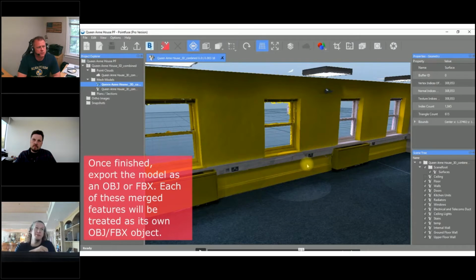One interesting note, mobile scan data meshes much better than terrestrial scan data because you don't have nearly as many occlusions or shadows. So if accuracy is the name of the game, you're probably not going to be wanting to use a mobile scanner anyway. But if you know you're going to be going a mesh route and you don't need millimeter accuracy on stuff, mobile scanning is a great fit for that because you just get much better, more evenly distributed coverage typically.